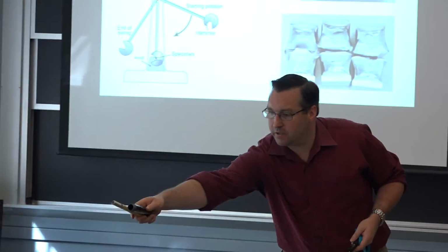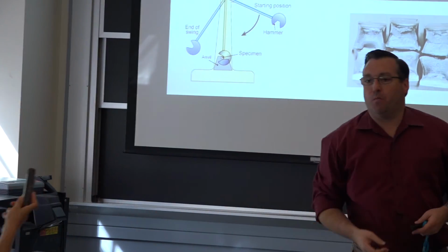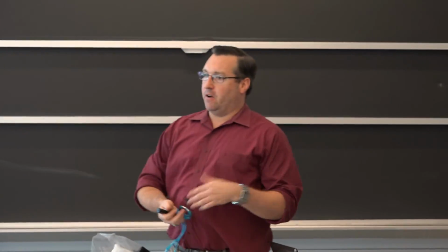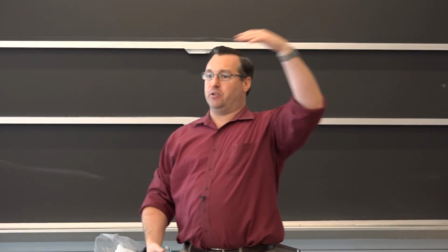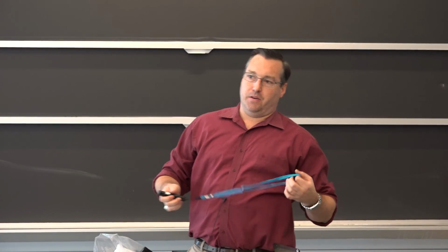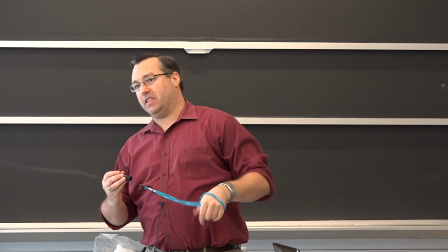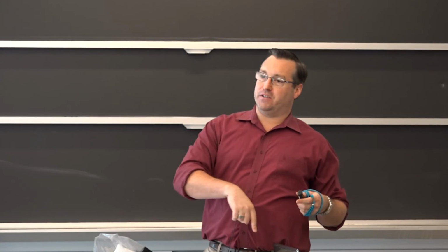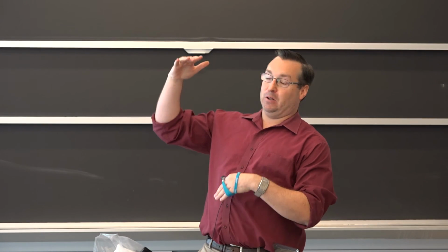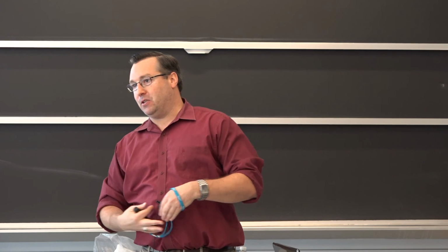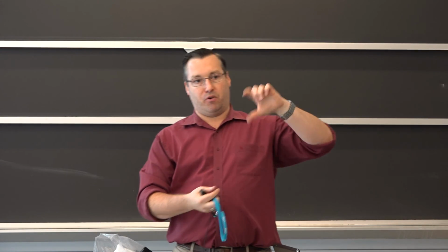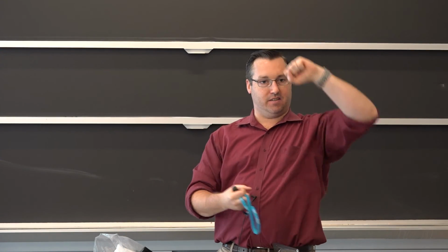You guys can see these too. Simulations rather than all of these? Well, the one thing is it costs a lot more. The video of the wire rope, that's a huge structure. The largest one that I've seen is at Lehigh University, and it's a 5 million pound load cell. They were actually doing full scale bridge sections where they would test these things to failure.